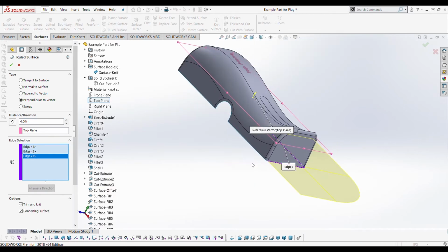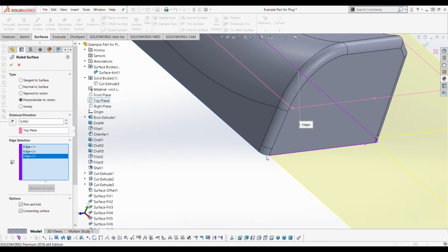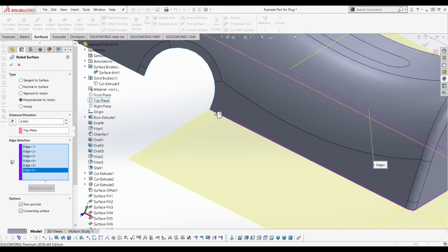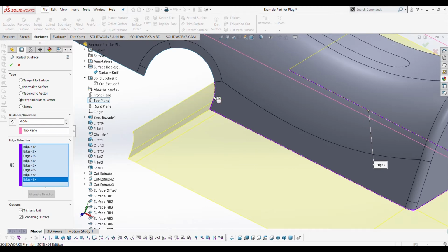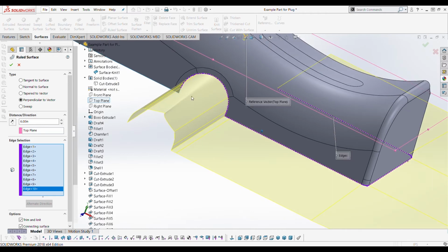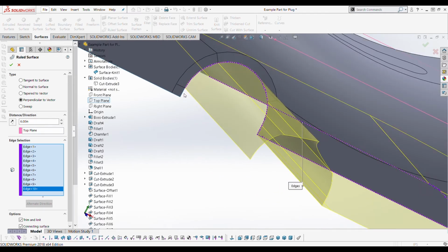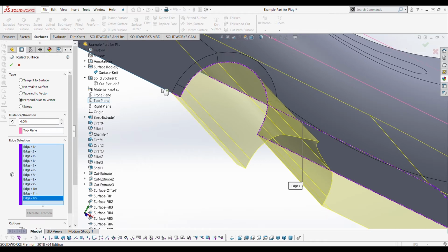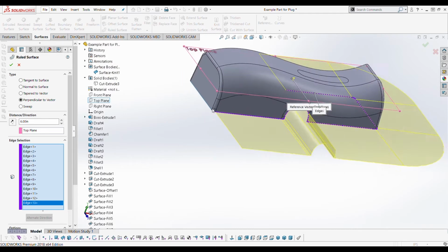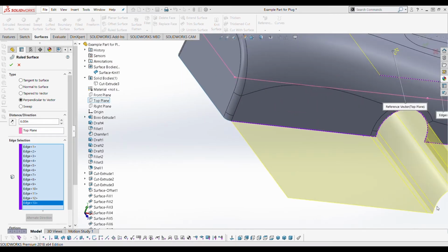If we are going straight to a mold, we definitely could reduce this down to the 4 inches or even less if you are going for a machined aluminum tool that you're not going to actually pull vacuum on. Maybe it's going to go into a press. But you can see I can select around these edges and it's going to maintain perpendicular. And I do see a couple weird things happening here, which is another good opportunity to see what we got going here.